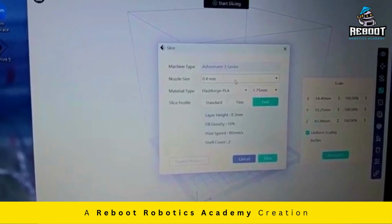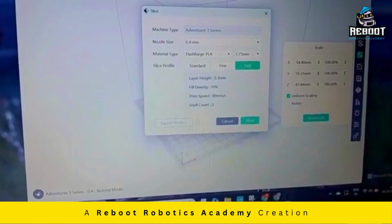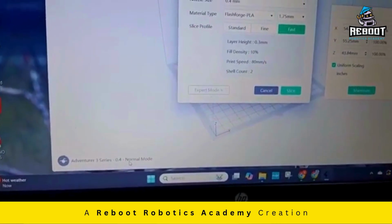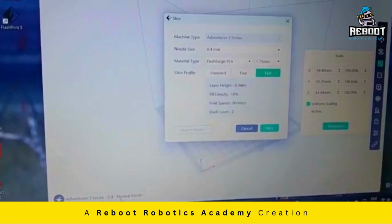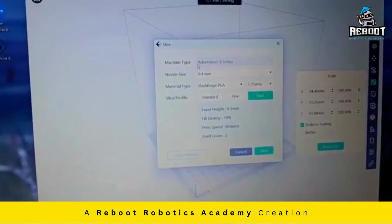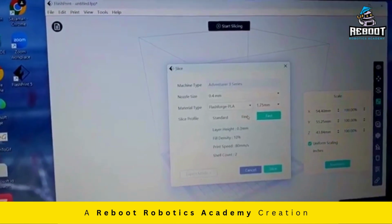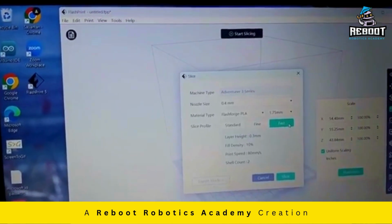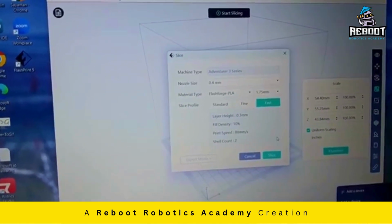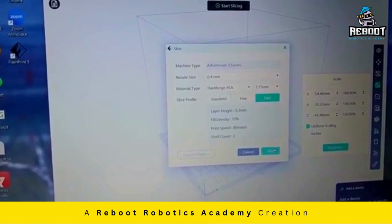All these specifications are mentioned over here just because we have already selected the printer series while the entire FlashPrint software setup was done. So all these default settings are showing over here automatically, and the machine type has been fixed to Adventurer 3, whatever we are using. Now over here, standard, fine, fast, these three are the options. So we are going with fast because we are just testing this model, and the main objective is to showcase this thing to all of you. So I'm clicking on slice.